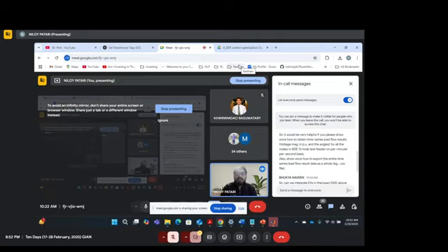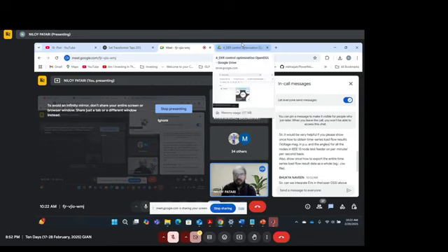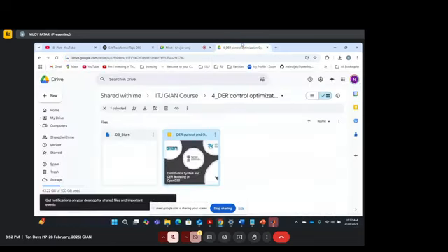So if you change the mode to hourly, it will do all the job. When you set the mode to hourly, you also have to put a load multiplying factor. So you can look into the OpenDSS discussions. I'm sure there is something, and if you don't find any, then I can take a look.